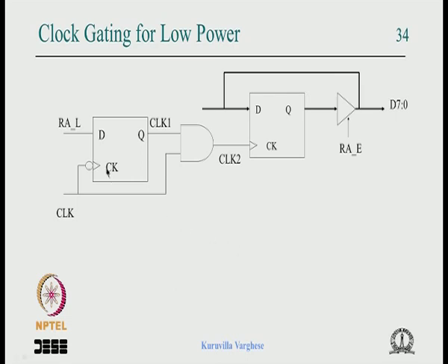So that is what is shown here. You have the latch signal which is coming from the state machine. Now we put a flip flop, and there is a clock which is coming, and it's a negative edge triggered flip flop. You see that there is a bubble, and so that means this latch signal is resynchronized to the negative edge. We are calling that clock 1, and that is ANDed with the original clock, which generates a clock 2, which is used for clocking.